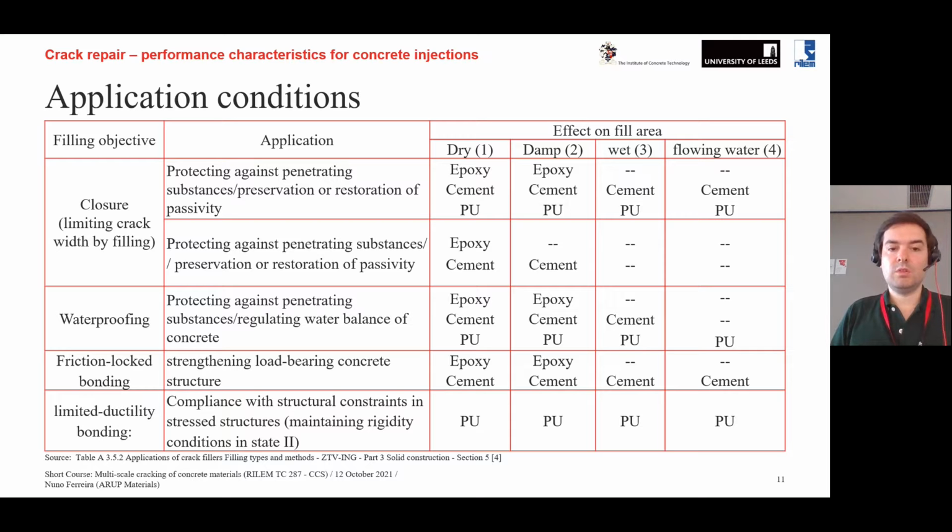So if we focus on the waterproofing, which is perhaps one of the most important use cases, we can see that epoxies really only work well in dry. Most of the epoxies, 100%, work only in dry situations. Some epoxies may work in damp situations. Cement, we can really waterproof a structure in most of the conditions, except if we have flowing water. So careful with this. But polyurethane is really a wide range, from dry to flowing water. It works.